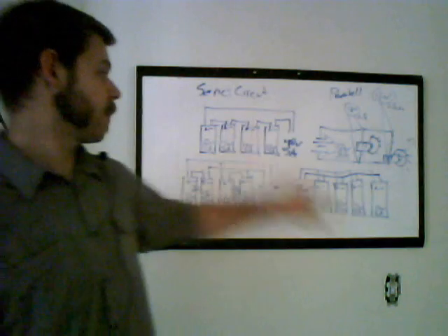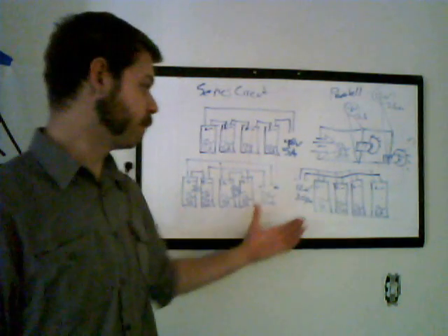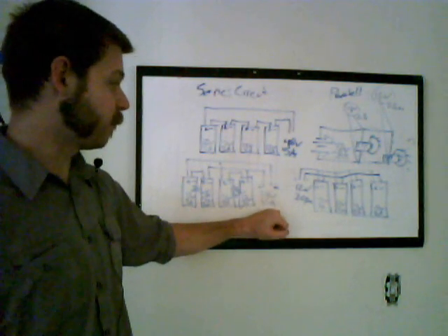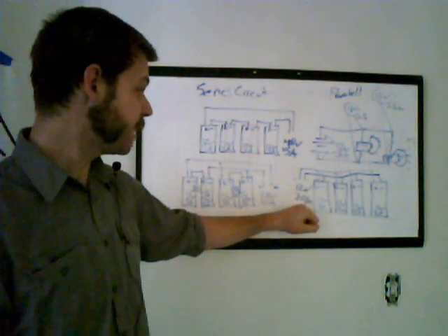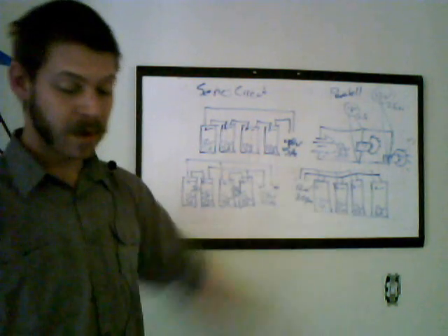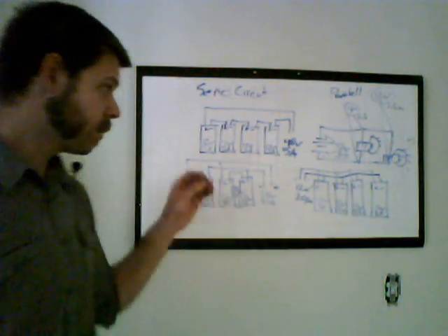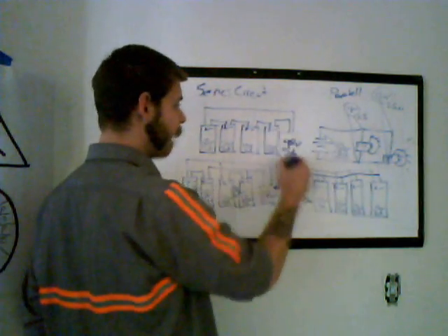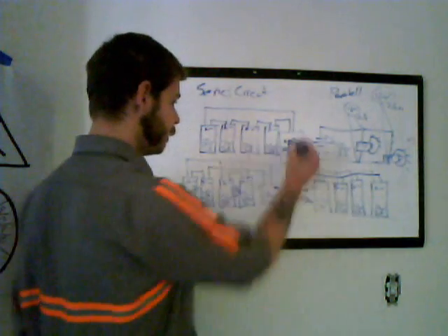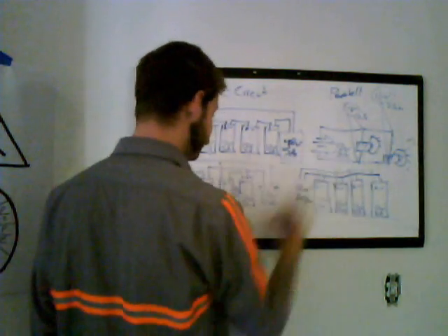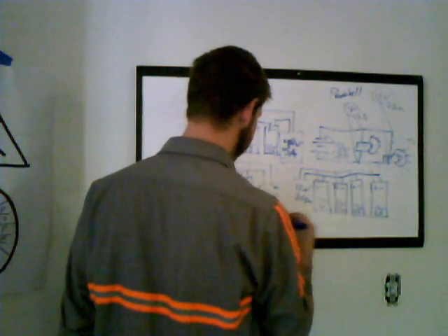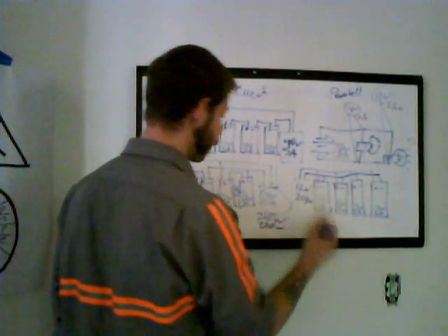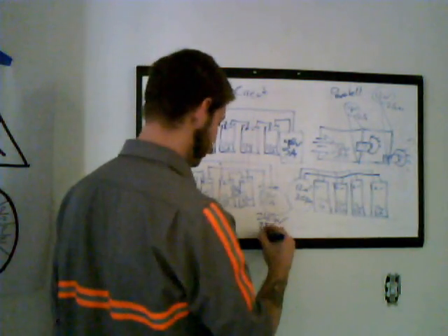These are the same 4 components. There are 4 cells that are 12 volts, 5 amps. You can get a 24 volt 10 amp system. You can get a 12 volt 20 amp system. You can get a 48 volt 5 amp system. The important thing about this is, as you recall, power is simply voltage times amperage. Take 48, multiply by 5 amps, you get 240 watts. You take 24 volts times 10 amps, you get 240 watts. 12 volts, 20 amps, 240 watts.